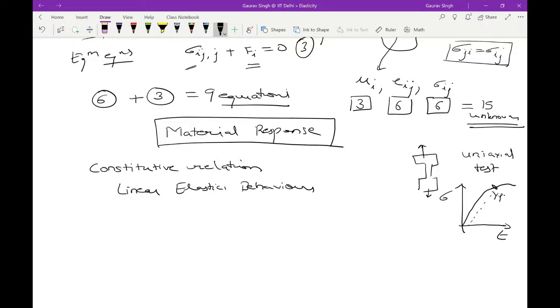If a material has yielded, meaning it has had a large plastic deformation or begins to have a large plastic deformation, then it is assumed to fail. So many of the failure theories are actually only considering the yield failure, not the final fracture where it breaks into two separate parts. Okay, so this is the topic about this.